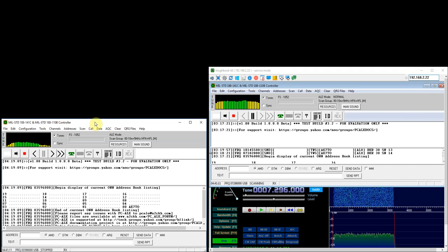And then once you figure out which bands are suitable for communications, you can send out a message from the net control station to the other stations, letting them know what band you all need to converge on. So again, right now I've got my receiver scanning 1 channel per second. I'm going to take my best guess at what band I want to use, and send a sounding on it.